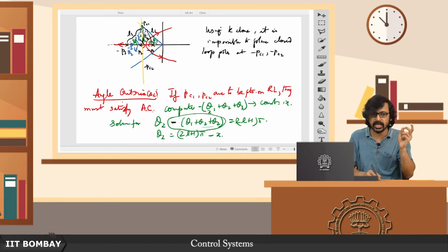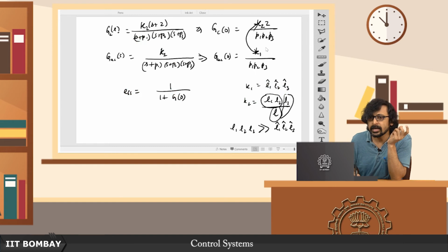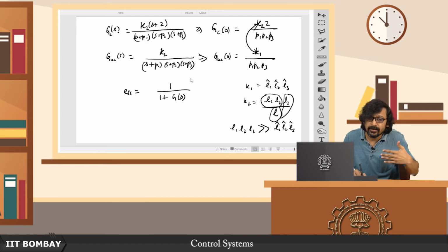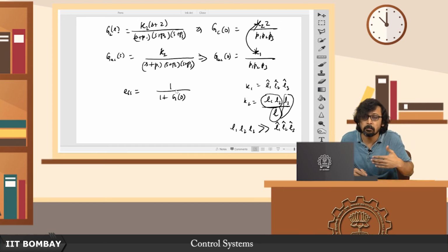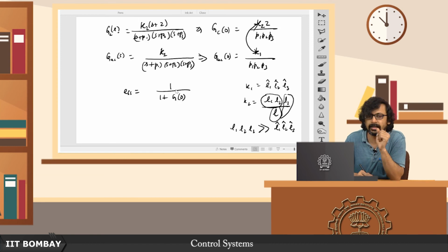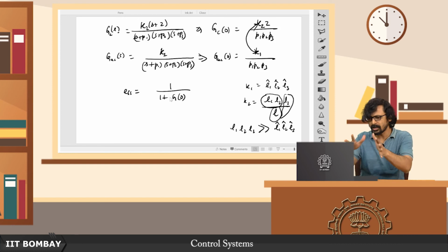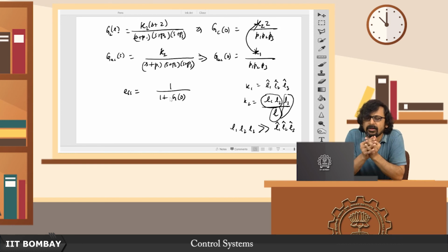Okay, so in general it appears like there is only a scaling factor of z, but in reality this K2 also increases compared to K1 in the uncompensated system, right? Okay, so therefore it has the effect of actually increasing this G0 manifold times, and that increase reflects in a lower steady state error. But you might still not be very happy with this.